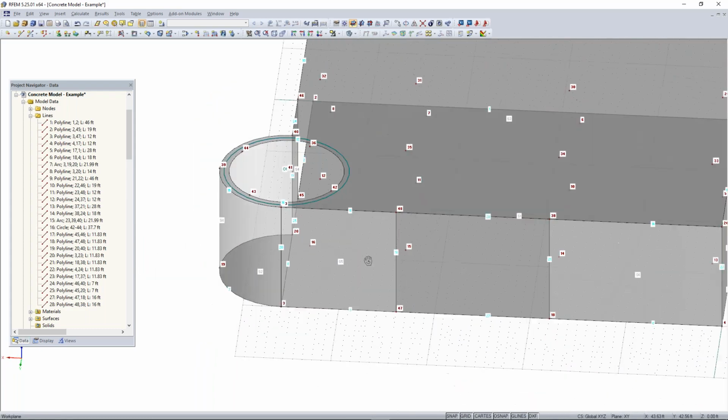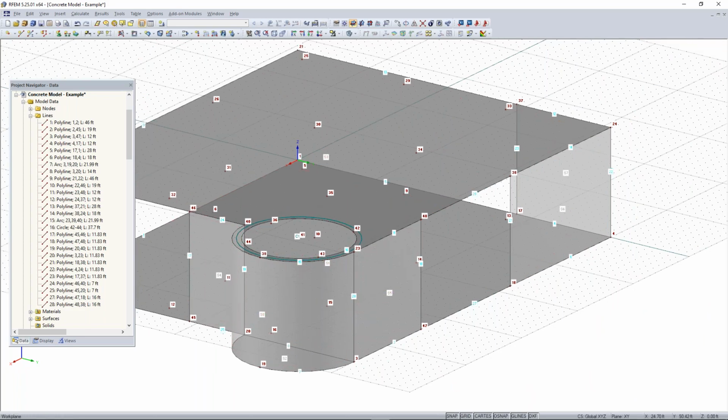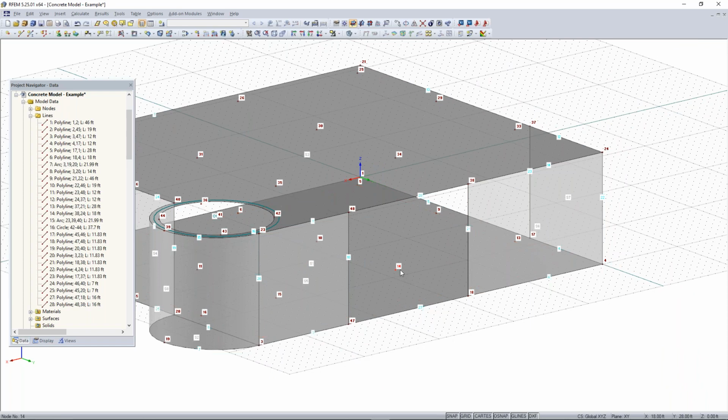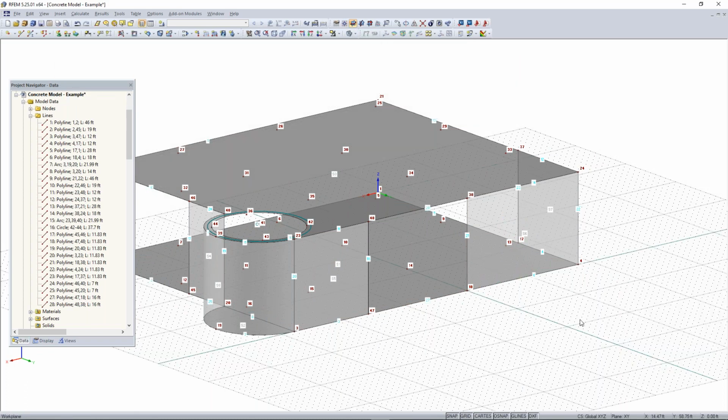So now we have basically all the walls to connect our floor slab and our ceiling slab. We're missing actually one more in the center, which will be our load-bearing wall. So what I need to do now is just change the origin of our work plane to node 18 here. And to do that, to change the origin of your work plane, you can go up here to this button called Set Origin of Grid / Work Plane. And then we can select node 18.